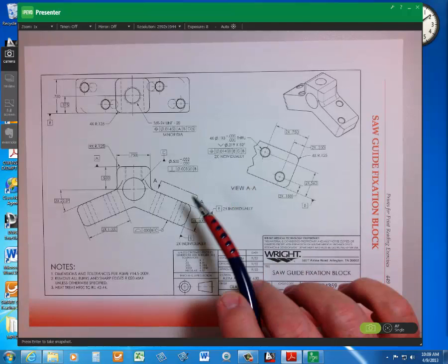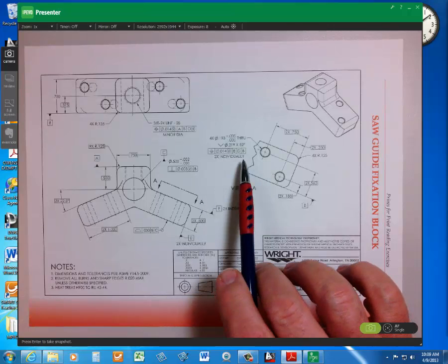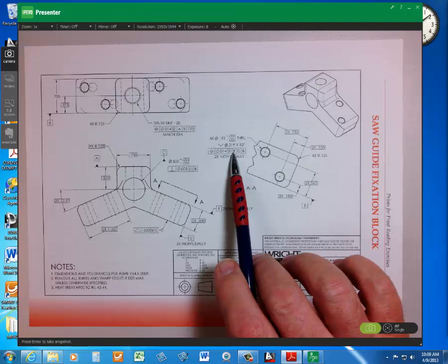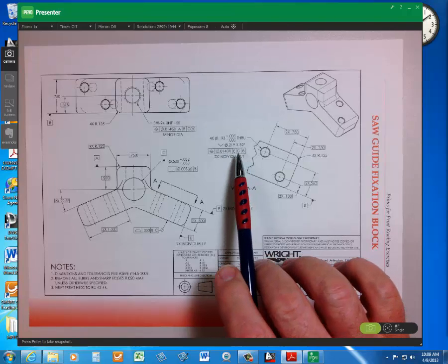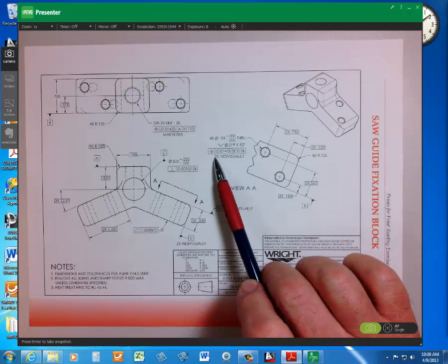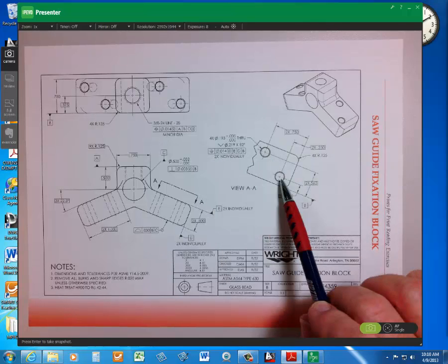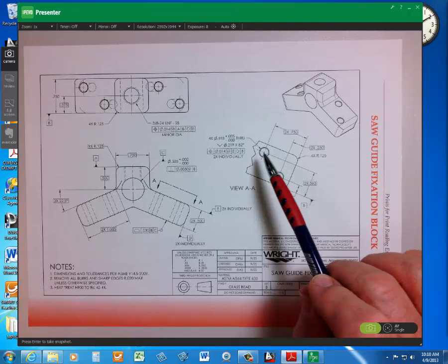So the note indicates that a multiple datum reference frame exists, okay, E, D, B, and that there are two separate datum features that need to be considered individually. Okay, so when we put this 2x individually, it means we're considering two of them individually from the other two.